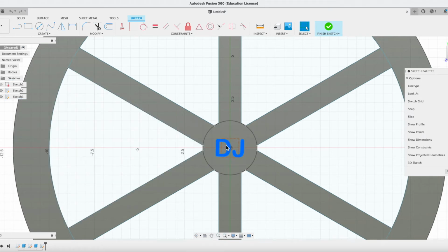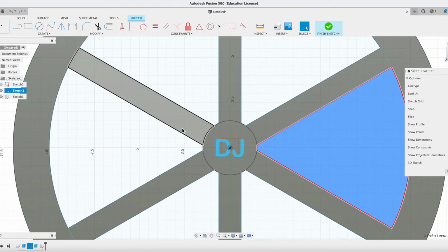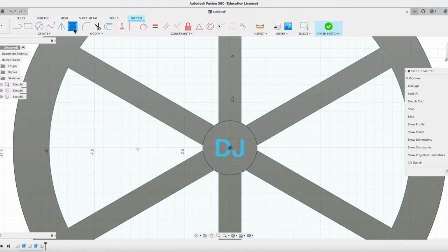Okay, so this is what we have after positioning everything. All I did was, because I think I made this a square, but I'll just double check, all I did was drag this up. You can do that, just let me show you. You can just hold, drag, and it's not working. Okay, that's because I already positioned it in the center, but if it's not positioned, then you can hold and drag. Or you can just dimension it, which is probably the easiest way. Oh, I was so close. Let's make it 1 inch, just to be rounded. And this was 1.01, so it was pretty close to a square.